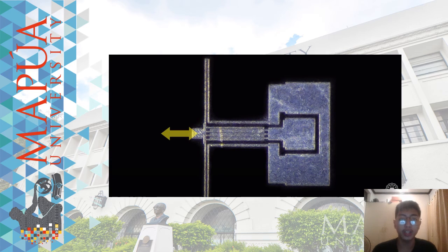So here's another electromechanical capacitor, except it senses acceleration on the horizontal axis. When the suspended mass moves in the horizontal direction, the surface area between the fingers changes, and then you can have some electronics to sense the change in capacitance.